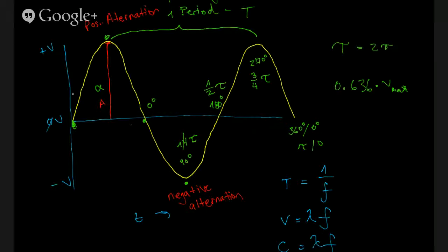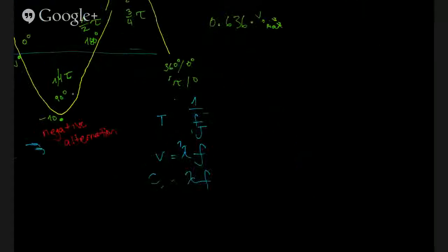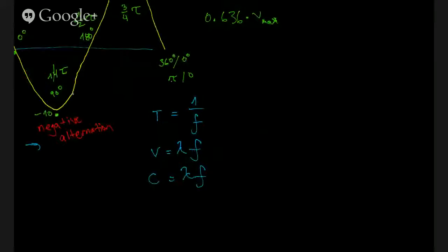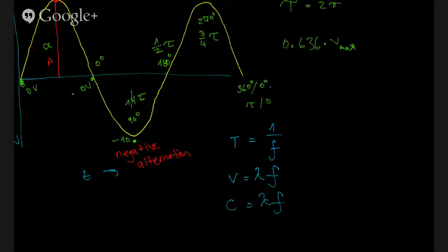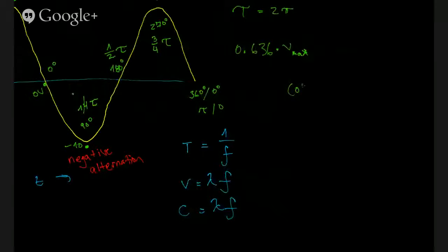We take all our samples and we say, well, 0 volts here and 0 volts there. And it's whatever V plus is, and it's whatever V minus is. So plus 10, minus 10, whatever. It doesn't really matter. We take those values, we square all of them and add them together. So 0 squared plus 10 squared plus minus 10 squared, 0, and so on and so forth.